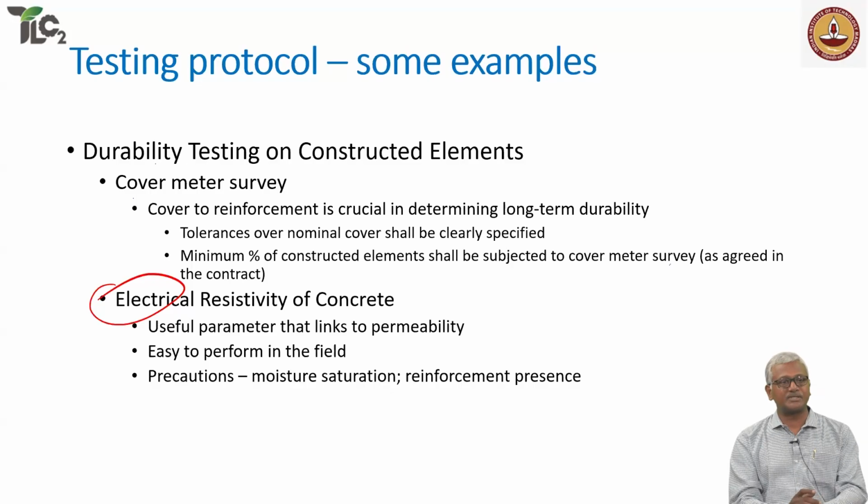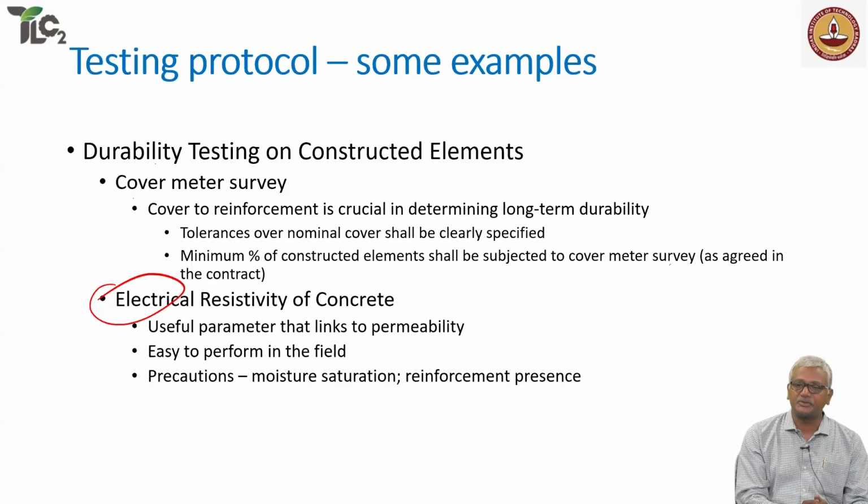And you can also do this on your specimens that are removed from curing for the testing for compressive strength. Just before testing compressive strength, you can actually measure the resistivity also. Establish some of these parameters so that you get confidence in using these instruments on site.